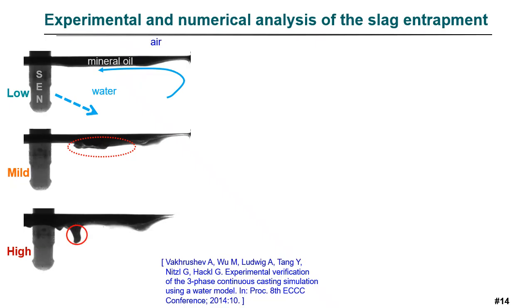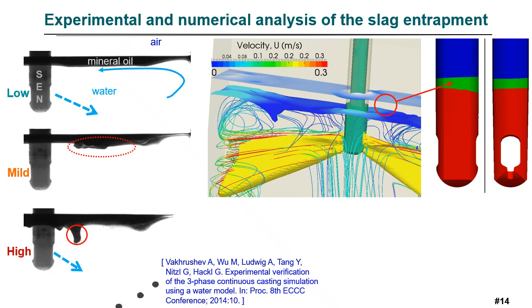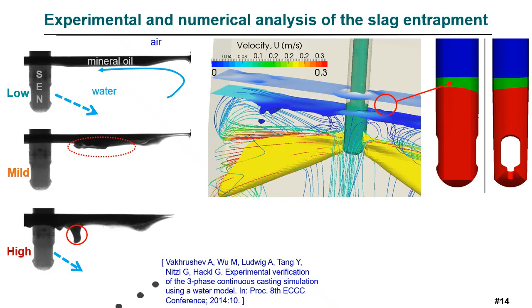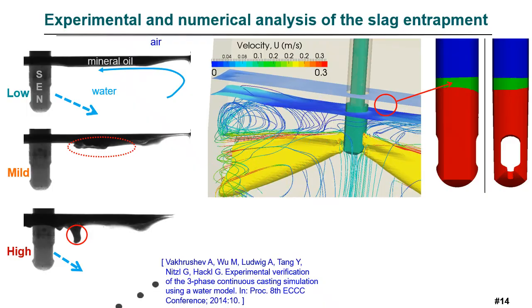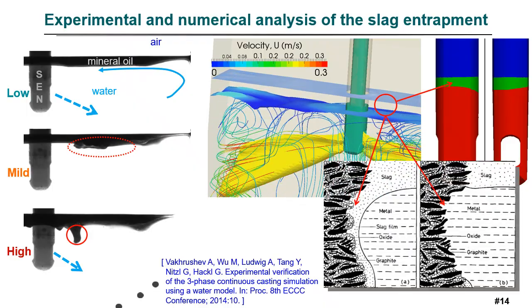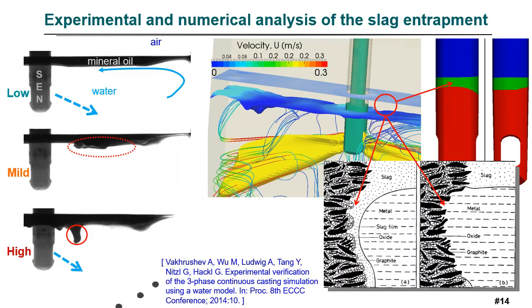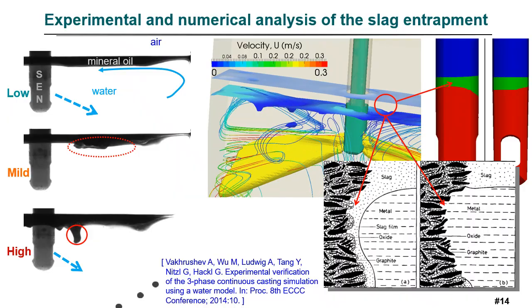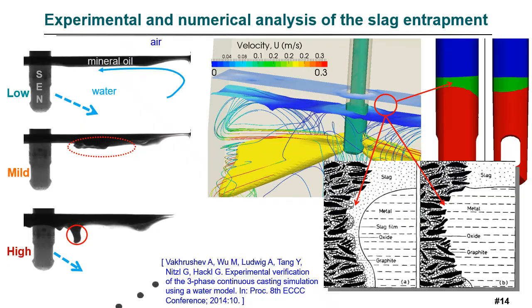a part of the slag droplet can be dragged away, but the most dramatic scenario happens when it meets a fresh melt jet. It emulsifies, and then it's almost impossible to extract it back to the slag layer from the molten steel. Additionally, we also investigate the fluctuation of the slag band layer, since continuous oscillation of this slag position can cause the erosion of the refractory materials.